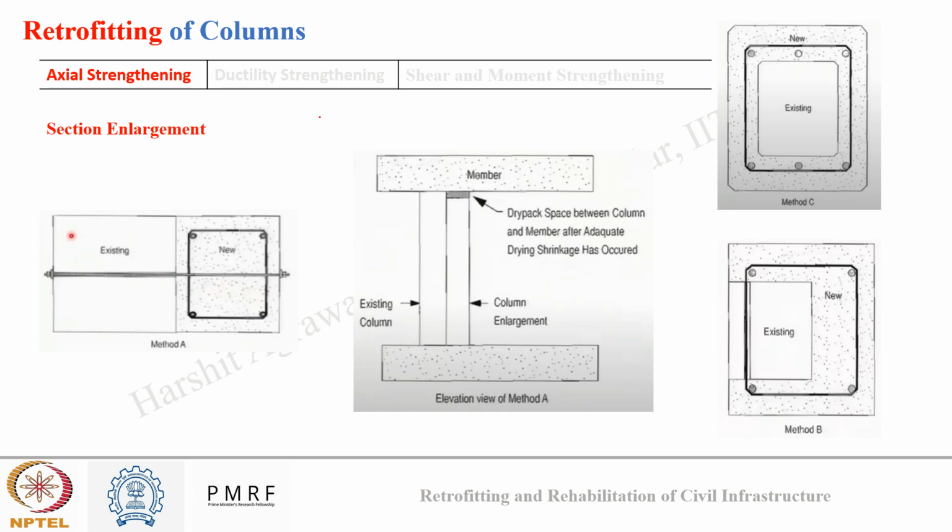After beams, which cover slab also, and walls, we have columns. For columns, the demand of strengthening can come for four major reasons: either to resist increasing axial stress, or to provide ductility for resisting bending stresses with minimum deflection, or for shear strengthening near support, or for moment strengthening near support. So let's understand each of them now.